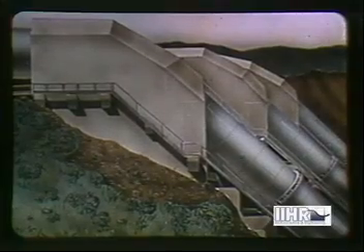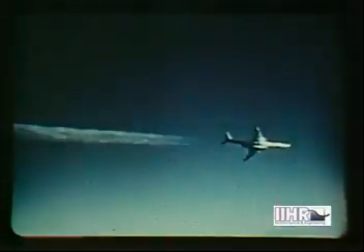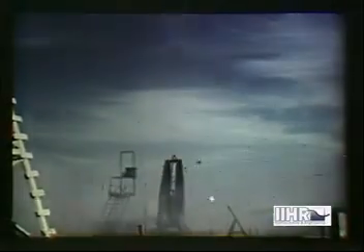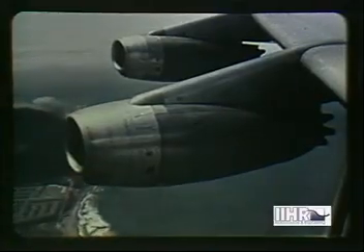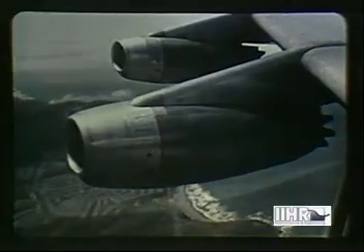If such forces are not statically counterbalanced, as in the sprinkler or this runaway balloon, then a useful means of propulsion is at hand. As a matter of fact, the reaction to jet formation is not only the most popular form of propulsion today, but in simplified terms, it is a noteworthy example of the interrelation of the three flow relationships. Whereas space rockets, like the runaway balloon, carry their own fluid to eject, terrestrial jets, whether air or water, can take in at the front what they later eject at the rear in accordance with continuity requirements.